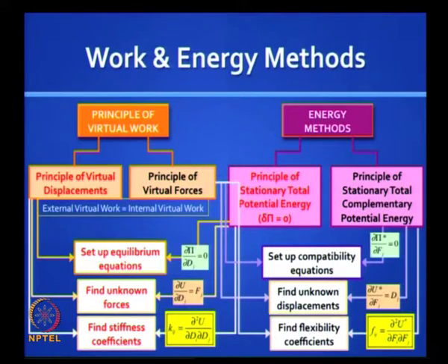So instead of setting up equilibrium equations, you now set up compatibility equations. Instead of finding unknown forces, you find unknown displacements. Instead of finding stiffness coefficients, you find flexibility coefficients. You are doing a similar exercise and you see a beautiful symmetry in these relationships, and you can do the same thing using work methods without getting into energy, and that would be a use of the principle of virtual forces.